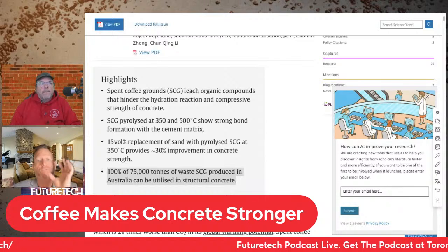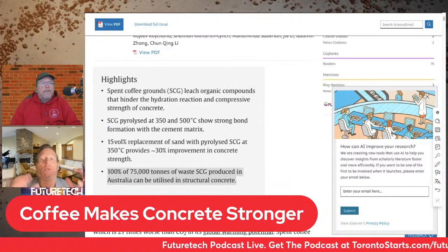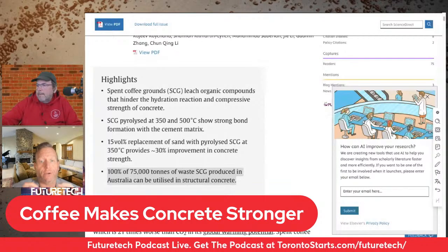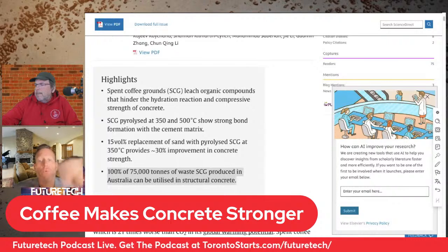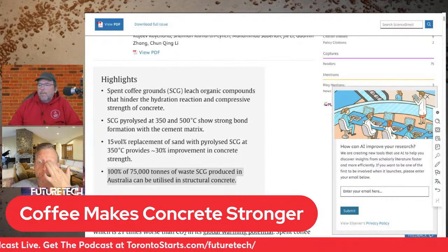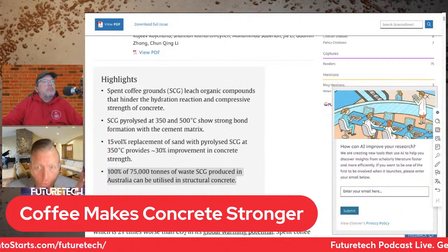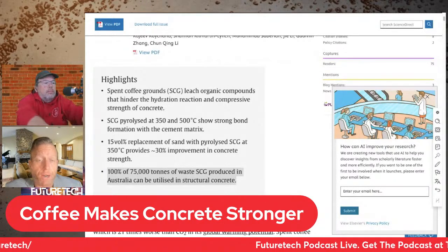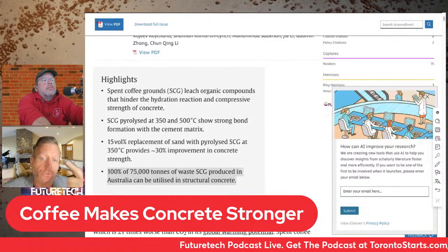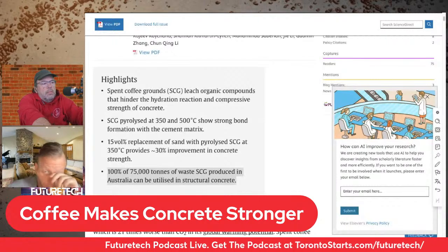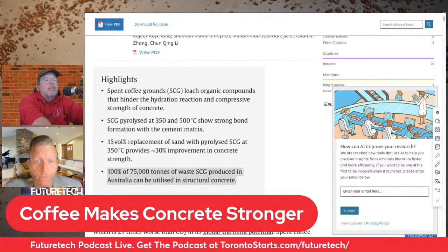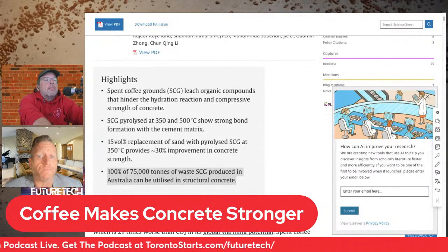So the coffee-derived biochar chemically and physically reinforces the cement hydrate binder phase of concrete through a bunch of these different mechanisms. The biochar integrates and strengthens the concrete's microstructure, which improves mechanical properties like compressive and flexural strength. So really cool way to leverage waste materials into this.